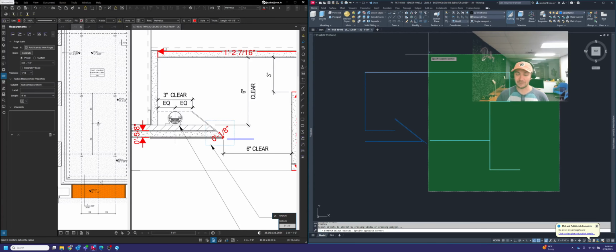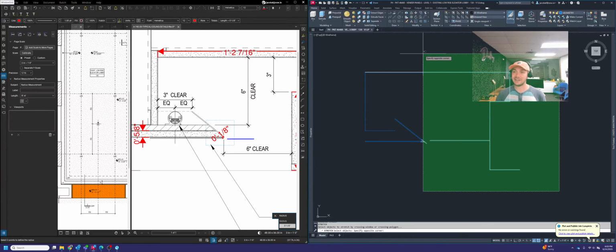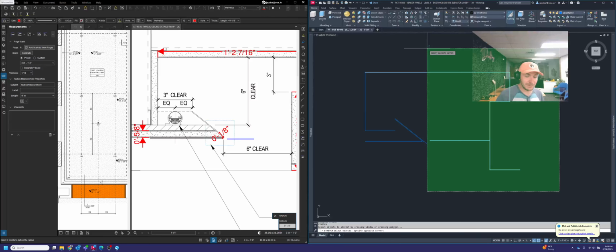Any line that's completely boxed in, for example, like right now, this line right here, is not going to shrink at all. What's going to happen is that line is going to move as I shrink the other lines that are half selected. So it's kind of hard to understand at first, but if you play around with it for a little bit, you'll definitely get the hang of it. So really what you want to do is always start in the bottom right corner of the object that you're trying to stretch, and you're going to want to move up to the top left corner.